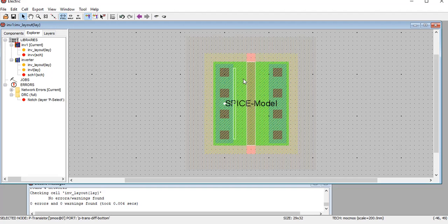See, if I keep clicking here, the moment you get a cross section with a white patch on the spice tool, leave the control button and drag it outside, and then press control I to edit the text and name it as PMOS.